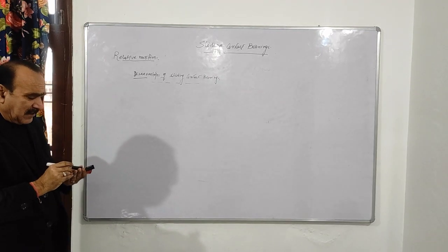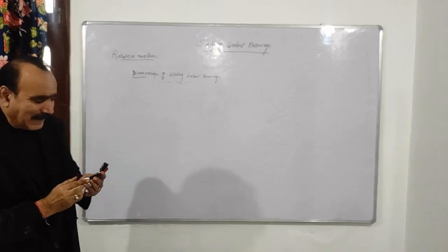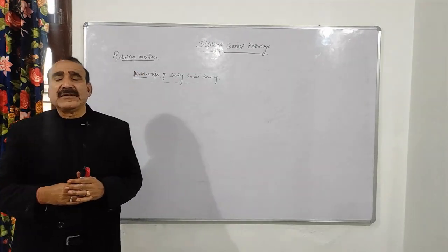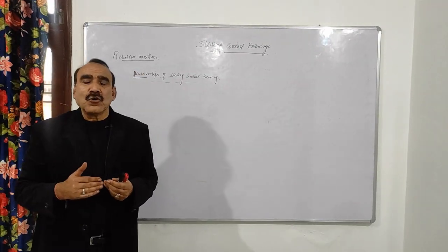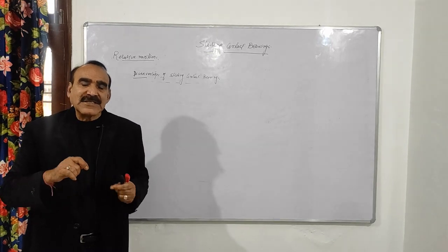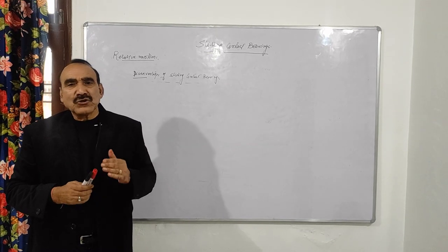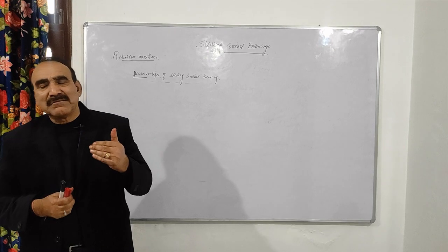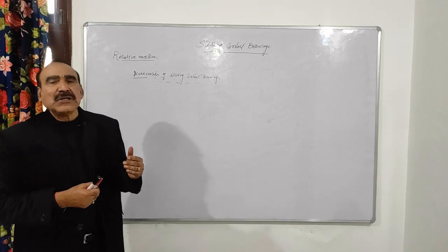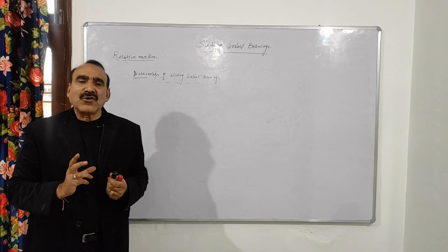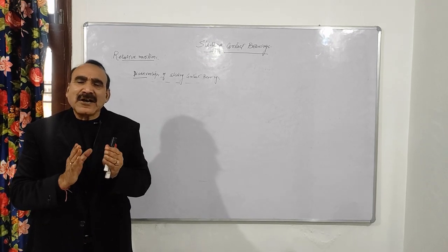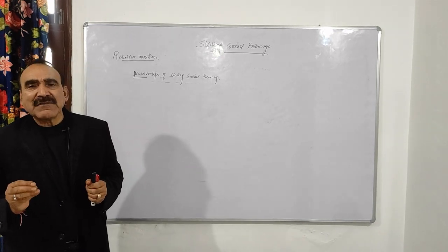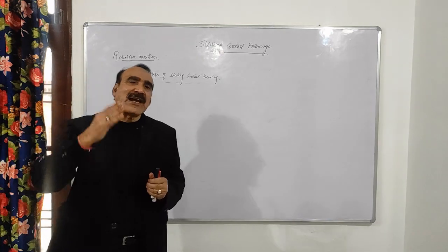सो सबसे पहला जो इसका डिसएडवांटेज है, जैसे मैंने आपको पहले बताया था कि इनिशियली जब यह ऑपरेटिंग स्पीड में नहीं होता, जब भी हम किसी इंजन को स्टार्ट करेंगे, राइट, तो जर्नल बेयरिंग का हमने बताया है कि it can sustain up to 1000 RPM, राइट। तो स्टार्टिंग में क्या होगा, वो ऑपरेटिंग स्पीड में नहीं होगा, it will take few seconds, you can say 5, 7, 10, 15 seconds to reach at this operating speed.